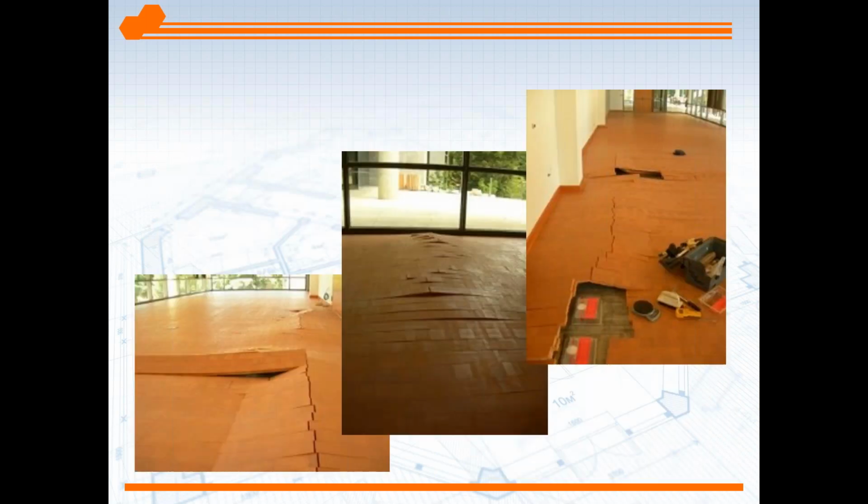If we take a look at the wood floor, the lower right, we see cupping, or upward curl of the wood components. This is a permanent problem. Once the floor dries out, that curl can be permanent. On the upper left, we see a tenting of the tile, a product of the wood swelling because of moisture and likely the lack of expansion joints between the wood pieces. So both these problems are permanent issues even when the moisture dissipates or is no longer present. Here we see some severe tenting of a wood floor.